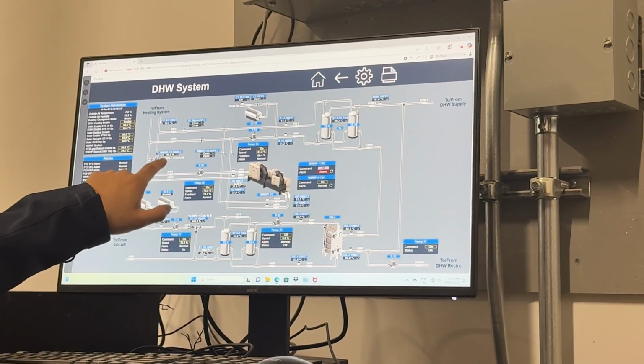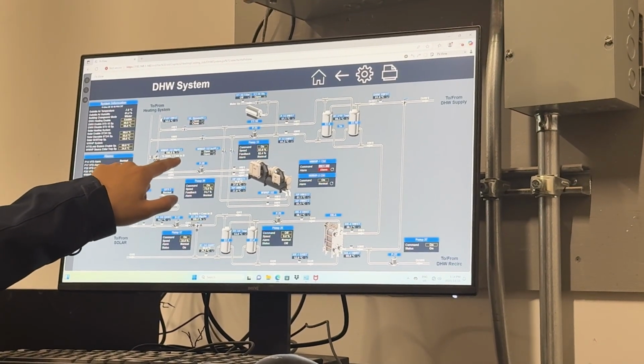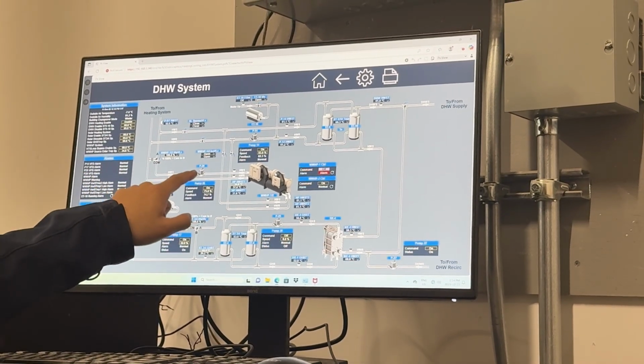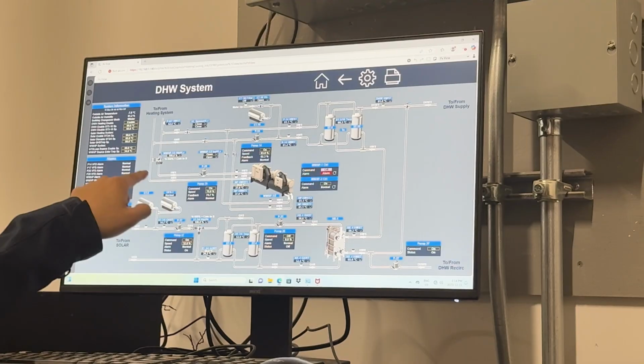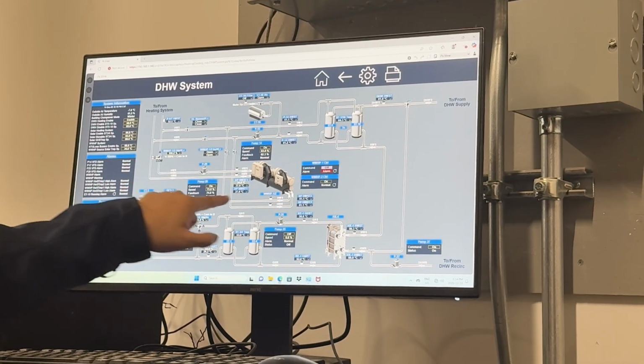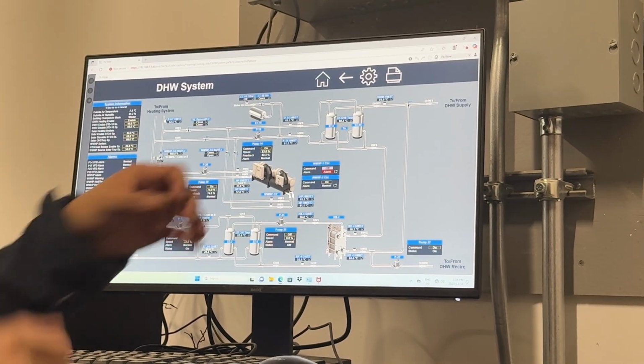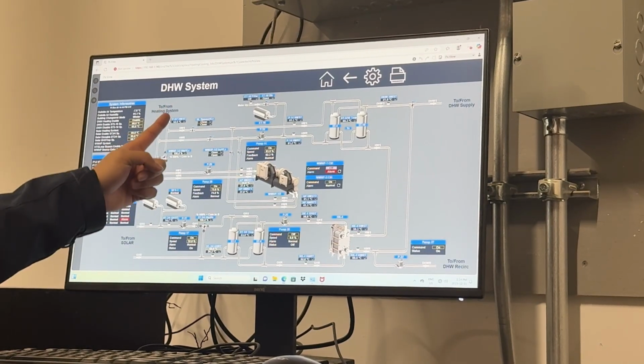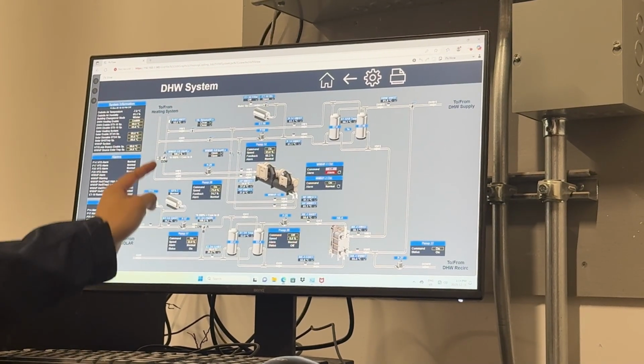See, right now it's 100%. It means 100% from common to B. So common to B, this is 100%. So the pump is running, it's just doing the recirculating in here. Just bypass it because the temperature is already happy, right? If temperature is low, we want a little bit more heat from this loop, then go back a little bit and do some.